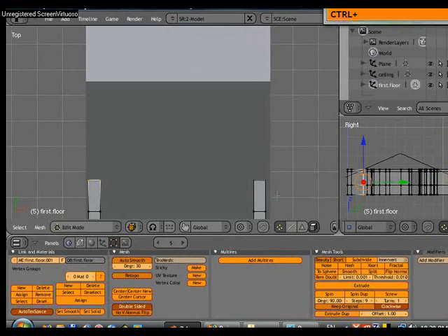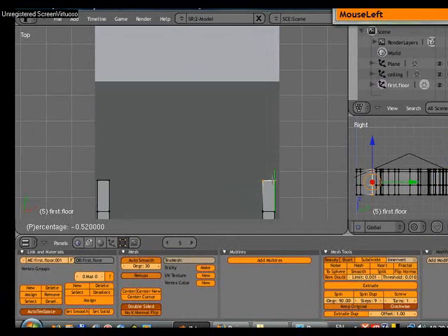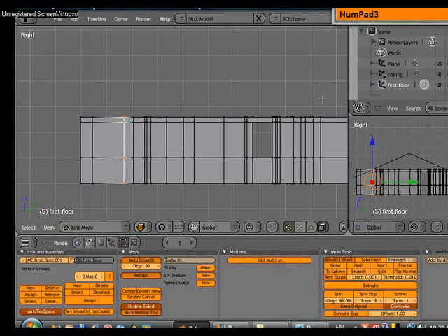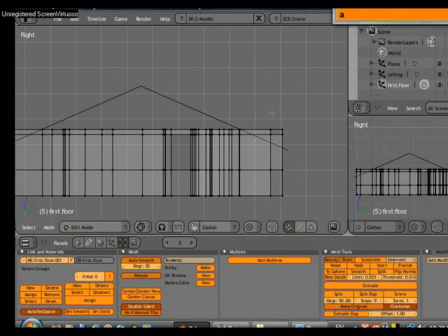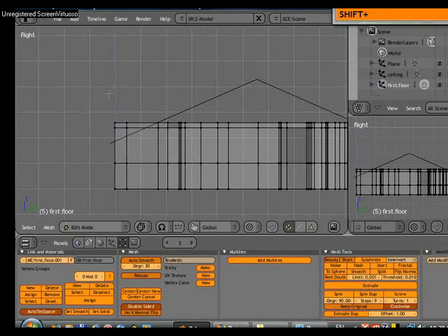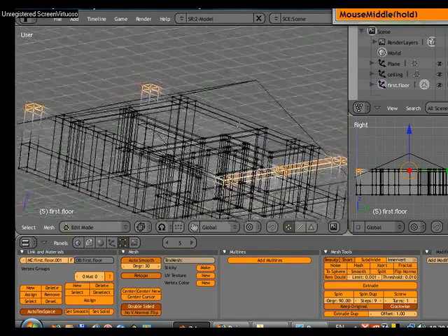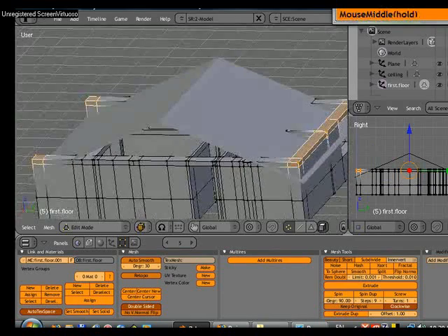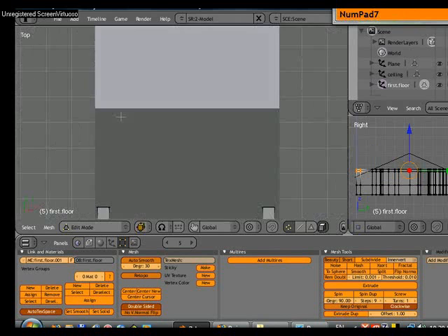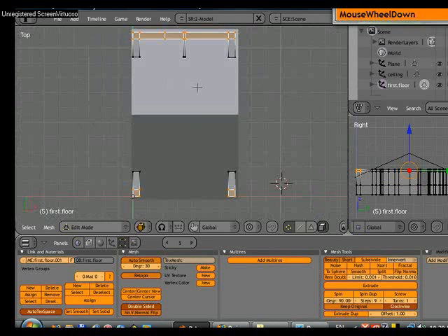It's pretty quick. I'll go to side view again. I'll go to transparent mode, and I will BB brush select all those vertices that are on top of the roof. Now I'll go to top view here, and I need to be in solid mode. That is important because I'll be using the retopo tool for that one. This doesn't work if you are in wireframe mode.